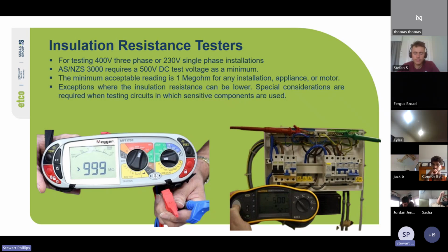Yep, you can do a 250 volt test. The main important thing is that you are testing your phase to earth. So what you can do is take the phase and neutral at the switchboard, twist them together and test between the phase-neutral and the earth.